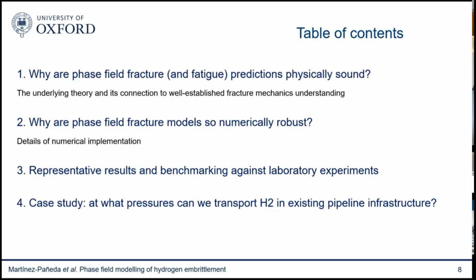Finally, I will move to some representative results in the context of hydrogen embrittlement. I will show how the model allows us to deliver an unprecedented degree of agreement with laboratory experiments. And then finally, since the focus here is on pipelines, I'll have a case study where we show that the method can be used to understand at what pressures we can transport hydrogen in existing natural gas pipeline infrastructure.